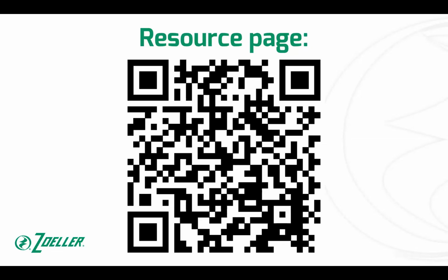My guess is that they're asking about lead lag, where your first pump's coming on and then your second pump is in standby mode, and if the lag float goes up, it would go on. So that might be what you're looking for. If you have any follow-up questions for whoever was asking that, please feel free to reach out to me directly, and we can have a deeper conversation on it. Just Zach@atspec.com.